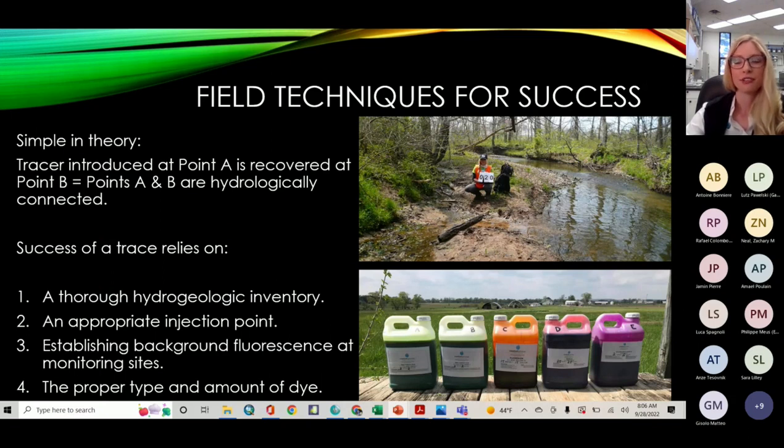As far as injection locations are concerned, you want to opt for something that shows evidence of a more direct connection to the groundwater. So you would be looking for characteristics like high acceptance rates at wells, or surface depressions and open sinkholes, or maybe you would look for soft or sunken soil, or even channelization towards a feature where you can tell that water is draining towards that location and then disappearing in the subsurface, which is what we see so commonly in karst environments, because we really have a great lack of surface drainage due to that prevalence of soluble bedrock near the surface.